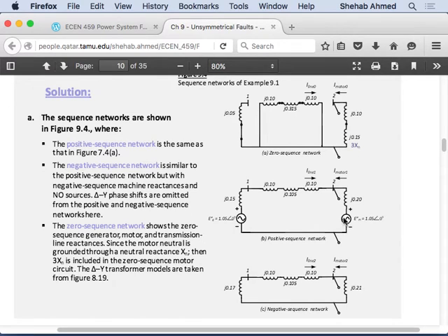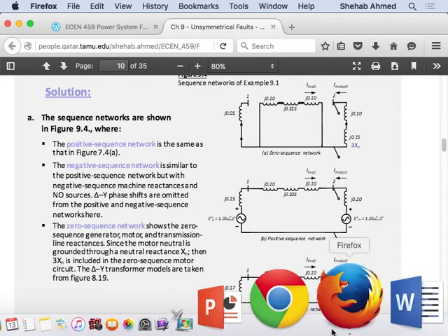How about for this? For here, you have 2 sources. Put the sources as short circuits. These impedances are in series, parallel with this impedance, right? So that will be your Z Thevenin. How about your V Thevenin? You put a short circuit. Remember, you're finding the Thevenin equivalent circuit, right?